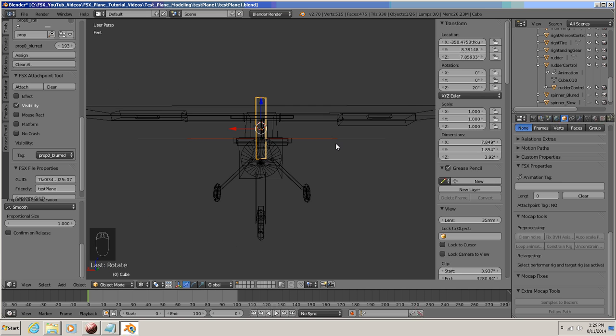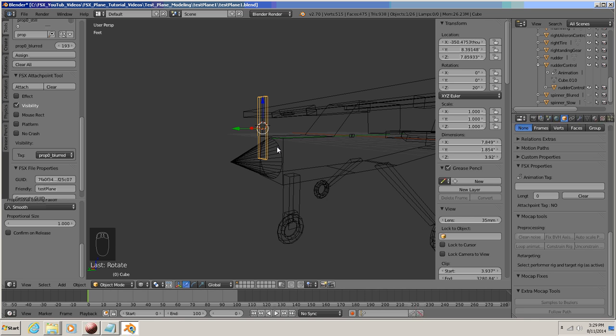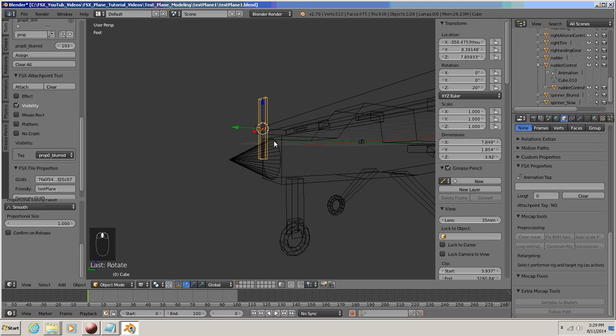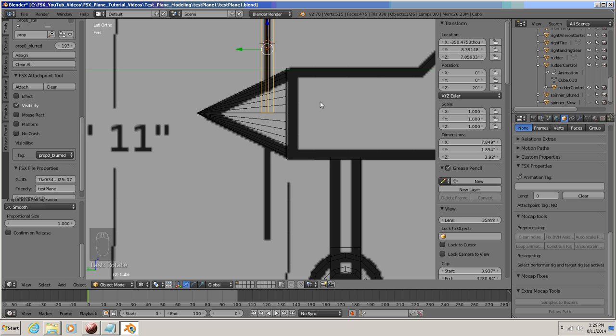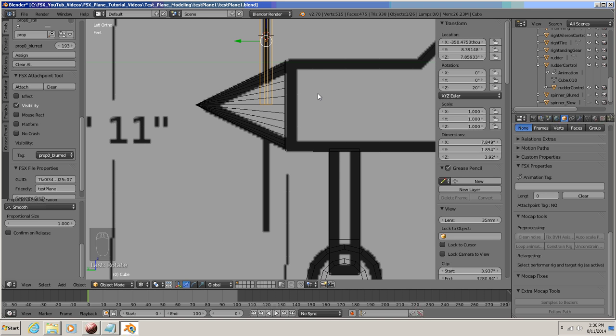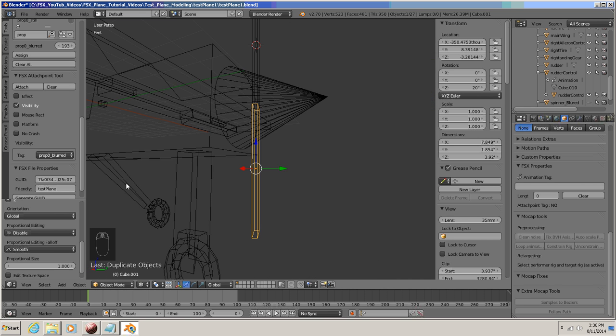Okay, that'll work. Now let's make a duplicate of it. I should have probably made a duplicate of it before we rotated. We could go and hit Control Z to redo it, then make a copy. But I think we're just going to drop it down and do a -40 on it, on rotate in the Y, and it'll do the same thing. So let's go to a side view. So Control and number 3. Let's zoom in. Let's do a Shift and D, hit the Z for the Z axis, and move it down with your mouse to about right there.